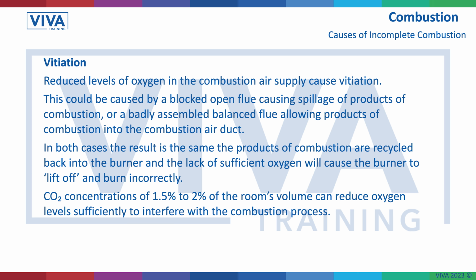For instance, an open flued appliance, an older appliance which is open flue, so a gas fire in a chimney, that's what's called open flue. The flue goes up outside, it takes this air for combustion out of the room. Now what we could get is spillage of products of combustion. That means the flue's got blocked. So what's happened could be Mr. Crow's decided to build a nest up on the chimney stack. Nobody knows it's there. So the products of combustion can't go out through the chimney, so they come back and go through the appliance. That's called spillage of products of combustion, and then it's coming back in.